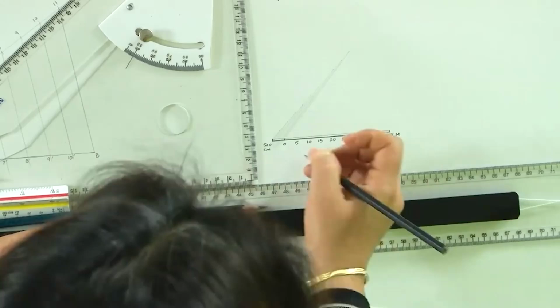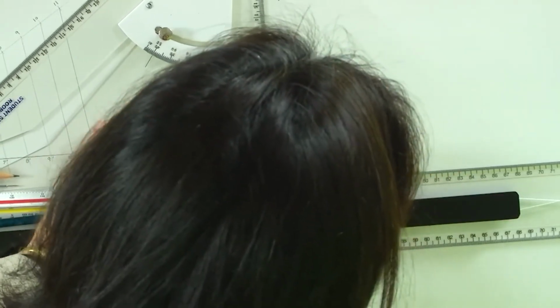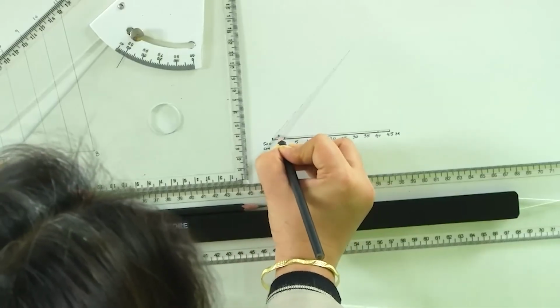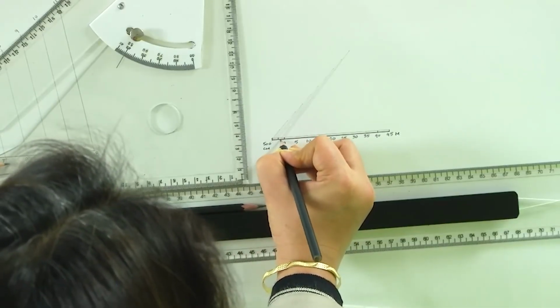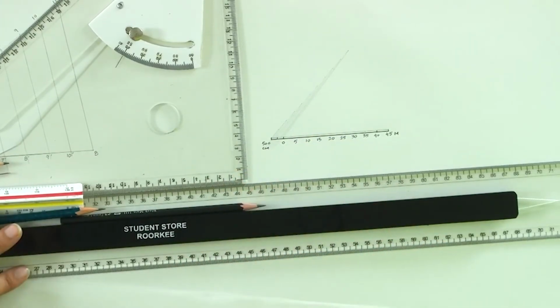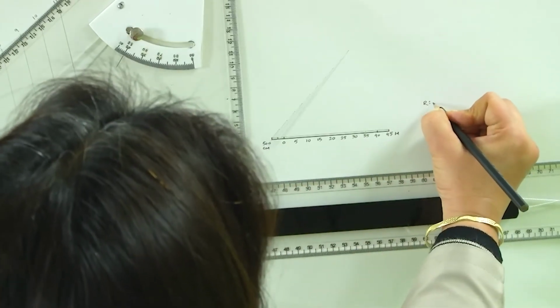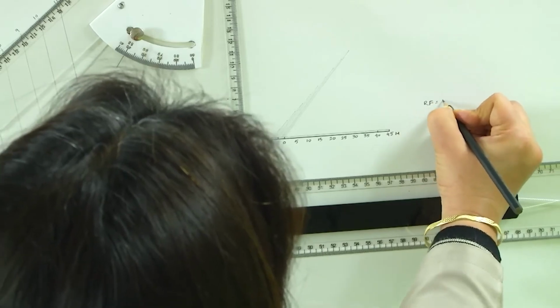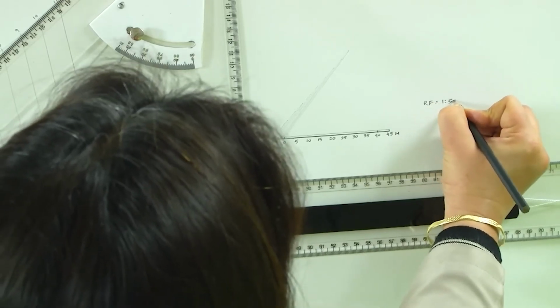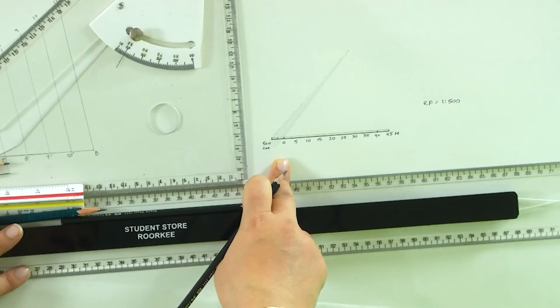This is a scale, and for each division we could also mark these lines, or we could just mark the middle one, which is 250 centimeters, or we could also write the divisions in between, depending upon the common unit, the dimension to be measured. This is a plain scale representing an RF of 1:500. That is what this particular plain scale represents.